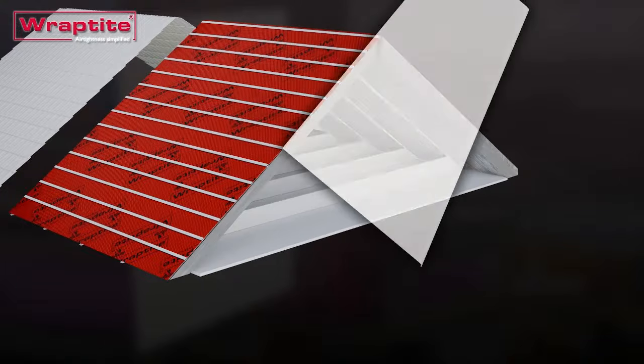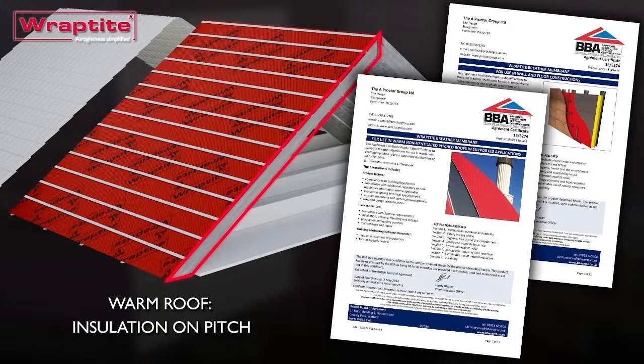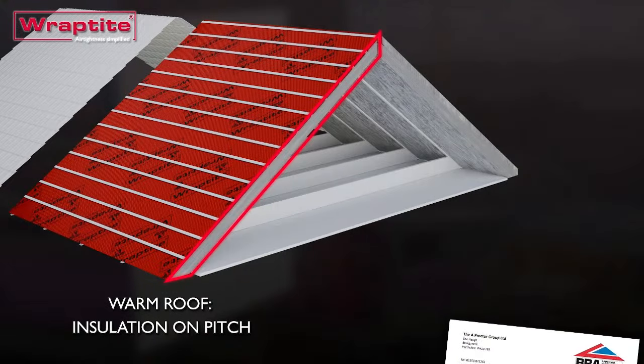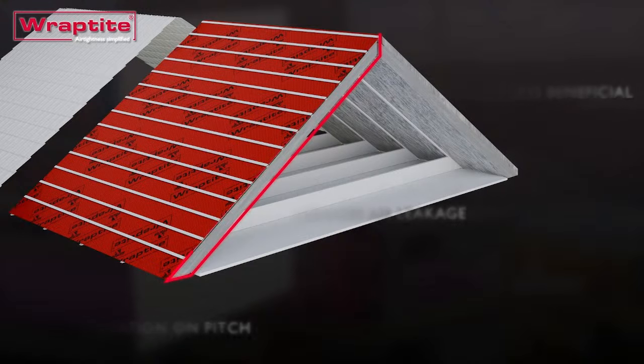The Wraptite self-adhesive air barrier is also BBA certified for roofs as well as for use in walls. But because it's airtight as well as self-adhesive, we only recommend it for use in warm, unventilated pitched roof applications. On a warm roof, the air permeability of Proctor air has minimal impact on the moisture performance, but utilising Wraptite instead can have a big impact on the overall air leakage rate of the building.